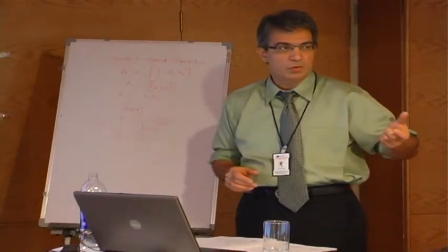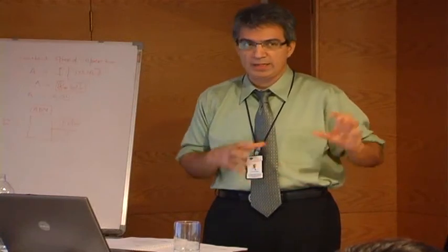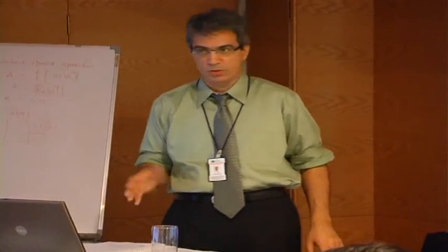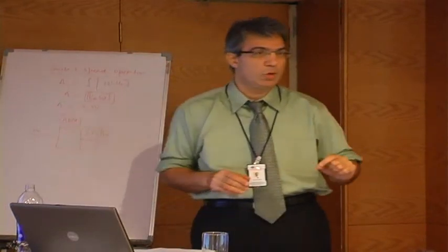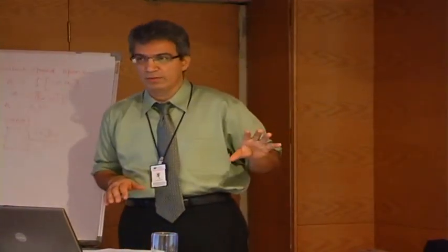And so we try to reduce our dependency. We can create a netlist from OrCAD and run on other Spice platforms, which is what we try to do, because we don't have any strategic relationship with OrCAD. So we tend to produce our models which can be used across platforms for Spice-based systems.